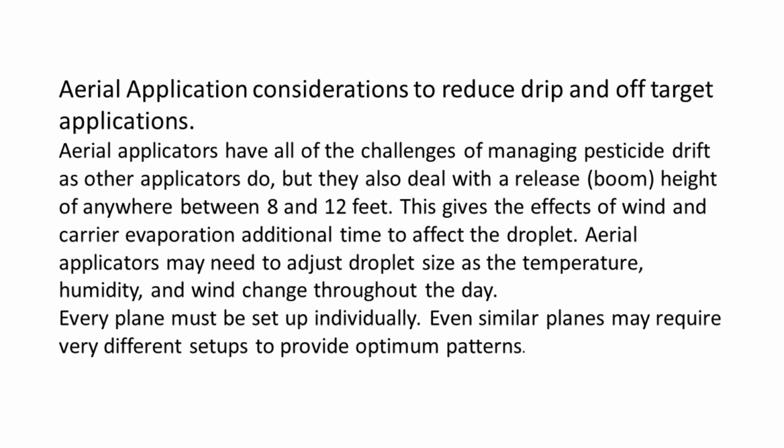Aerial application considerations to reduce drift and off-target applications. Aerial applicators have all the challenges of managing pesticide drift as other applicators do, but they also deal with a release boom height of anywhere between 8 and 12 feet. This gives the effects of wind and carrier evaporation additional time to affect the droplet. Aerial applicators may need to adjust droplet size as the temperature, humidity, and wind change throughout the day. Every plane must be set up individually. Even similar planes may require very different setups to provide optimum patterns.